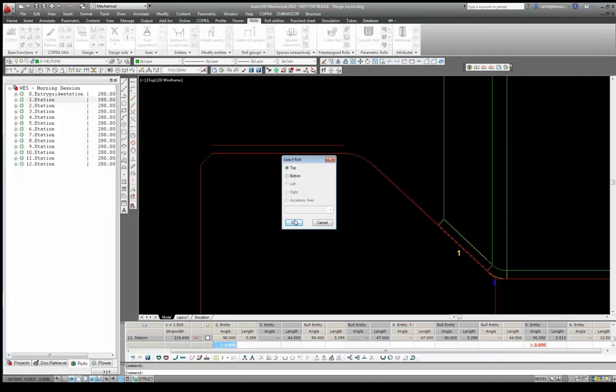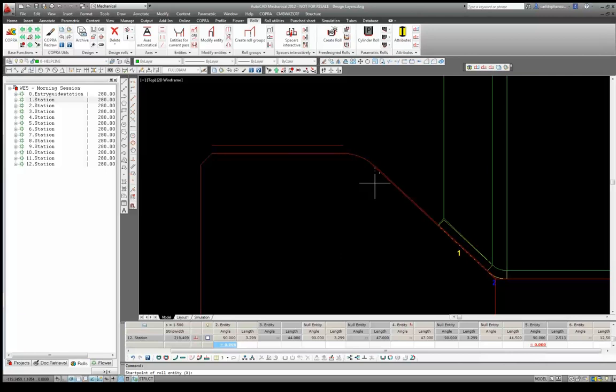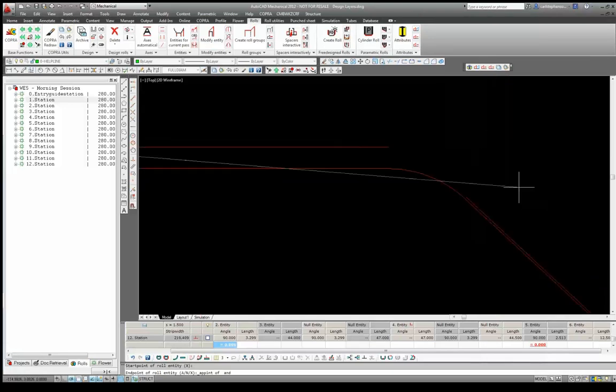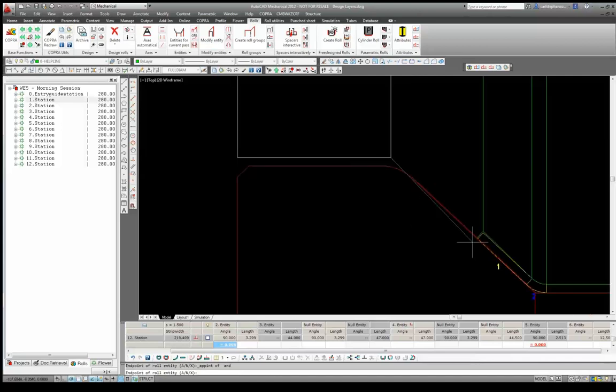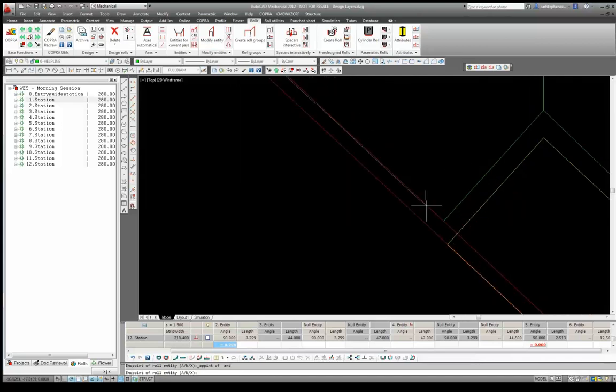OK. And it will begin from over here, so I can use my object tracking tool in AutoCAD to specify the entity start point, just by hovering over the lines here. To the apparent intersection of here and here, and now using the object snap tool to the endpoints here to here.